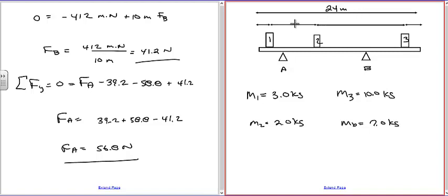And it has to add up to 24. So we're going to make that 2. We also need the distance to the supports. So let's put that distance from here, and then we'll do the distance between the supports. Actually, let's do the distance from both ends. You just have to make sure you don't over-specify things.